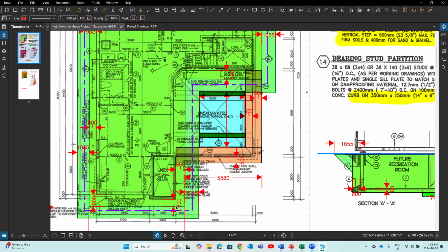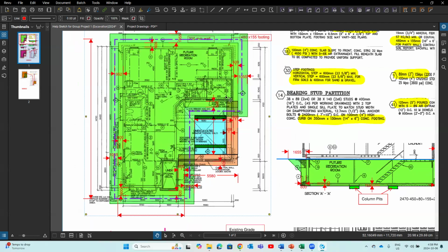So pay attention to those kinds of small things. When we excavate a big basement, we use equipment. We don't want to make those setbacks; we always cut it straight. So the same situation applies to this side. You see this wall here has a setback there, right? So we should base on this wall to decide the workspace. From this wall out 600 millimeter. So that's how we draw this first part of the excavation under the foundation plan.